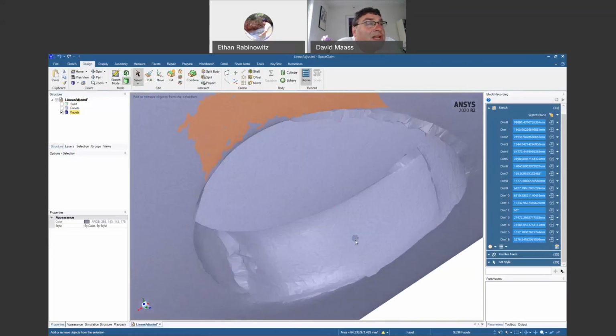Oh, okay. So you're selecting facets and then fitting a cylinder. Exactly. Yep. I haven't fit the cylinder yet. I'm going to select facets and then fit the cylinder. Exactly. Okay. All right. And so, yeah, holding Control allows me to add to my selection. Double clicking is what grabs it by angle. And then dragging this little slider up will expand and increase that angle to select more.